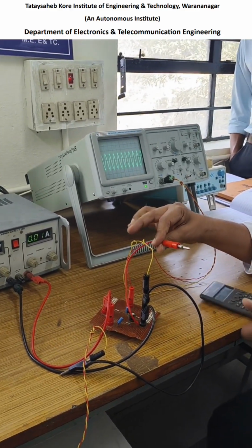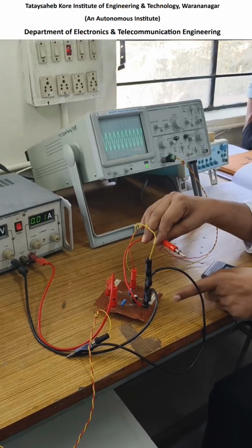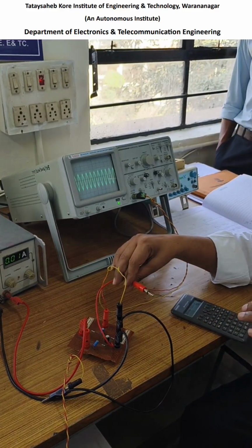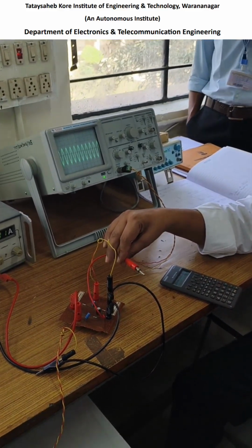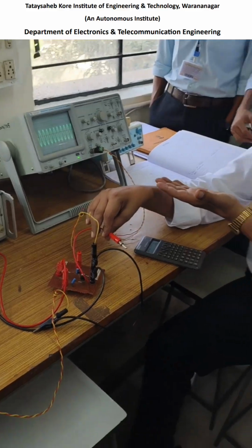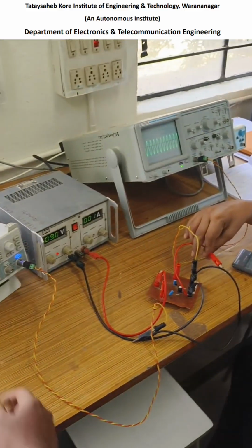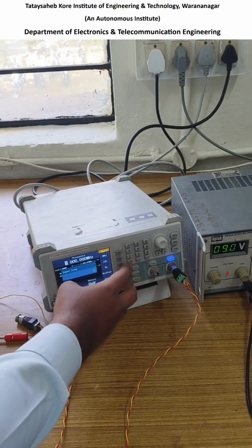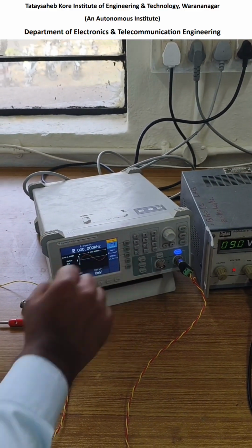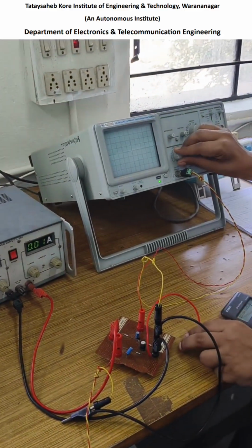So when you are keeping this open, once again I repeat, it is acting as without feedback. So I told you, if you connect this signal here, it is acting as without feedback. And I told you, when feedback is not there, the gain of the amplifier will increase. Now very simple, just make it 5 kilohertz first. Right? Now here you check.